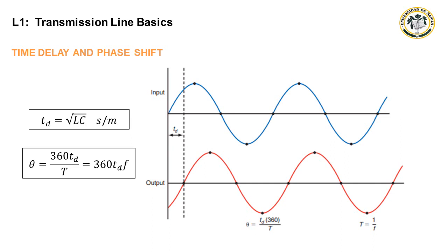Obviously, a large roll of coaxial cable is not a convenient component in modern electronic equipment. As a result, artificial delay lines have been developed. These are made up of individual inductors and capacitors connected as a low-pass filter to simulate a distributed transmission line.